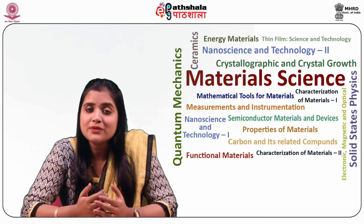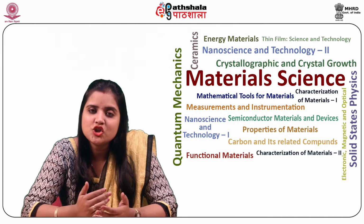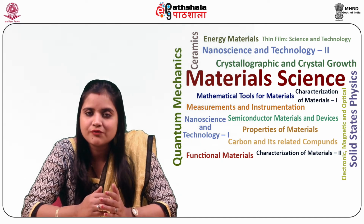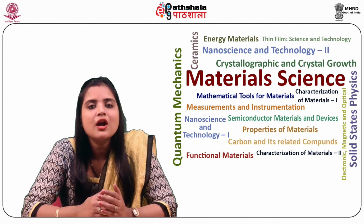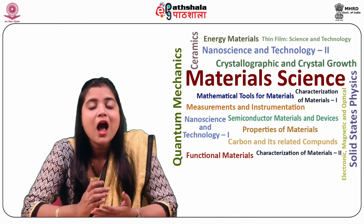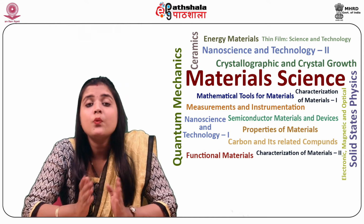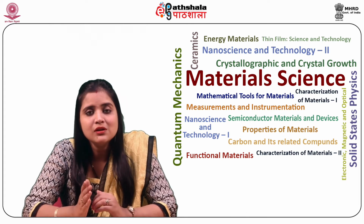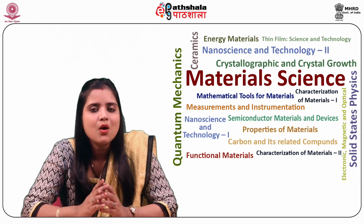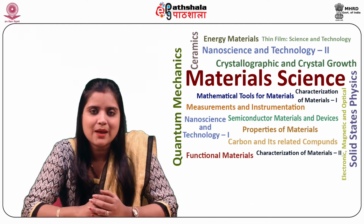The results from the extensive study of properties like conductivity, temperature dependence, and thermal stability have led to the application of thin films as resistors, interconnections, and contacts. Such properties of thin films are highly structure dependent. The conductivity of thin films varies with the orientation of the normal to the surface with respect to the crystallographic axis, even for materials having cubic symmetry, such as silicon, for example.